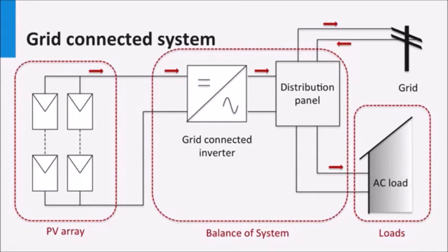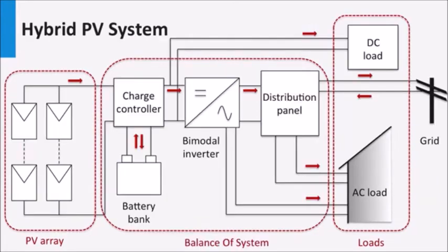In this case, the PV system is grid-connected. The load can depend on the PV system as well as the grid for power. There is an exchange of power between the grid, the inverter, and the load. The inverter latches on to the grid frequency and voltage. The inverter's main task is to only pump power into the grid. So the inverter supplies AC power to the grid as a current source, while the role of the constant voltage source in the system is fulfilled by the grid.